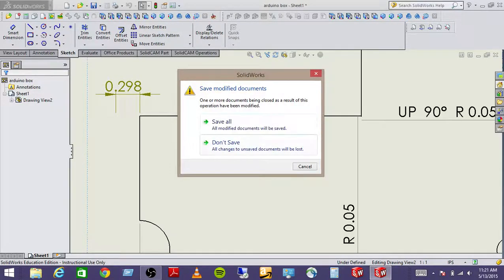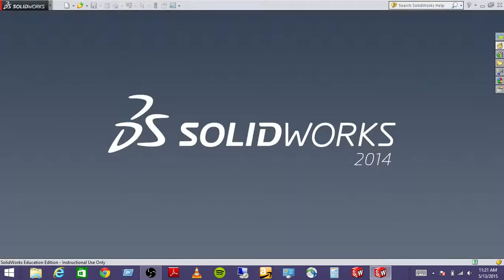And then I wanted to reiterate, this is a common theme with aerospace students that we see. You need to know when to use the laser cutter and when not to use the laser cutter. Remember, the laser cutter cuts by melting. So at the top of your part, it's going to melt more than at the bottom of your part as the laser comes down in.